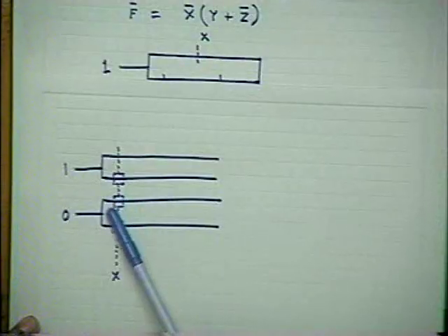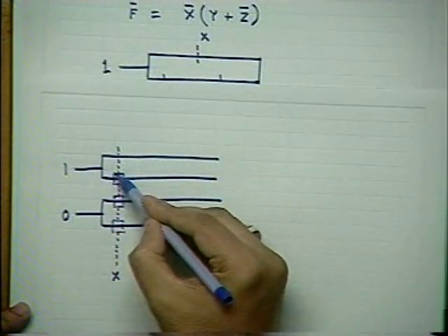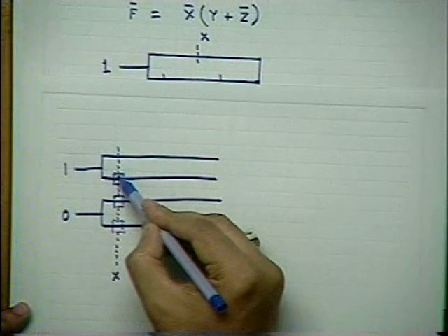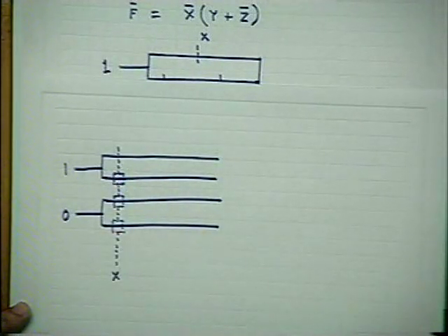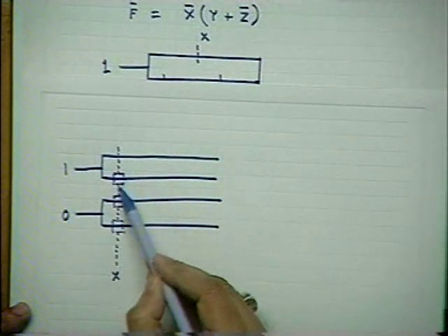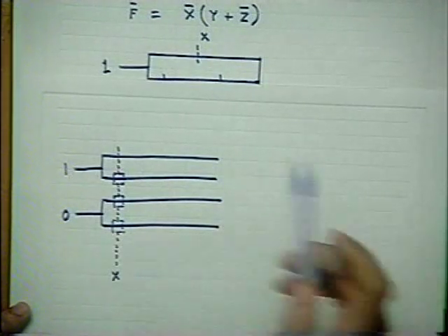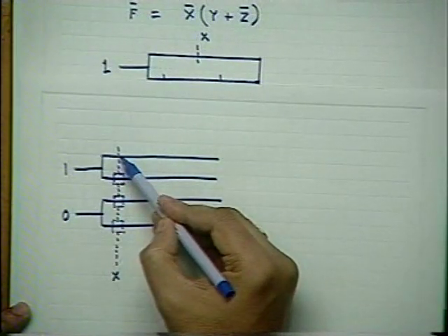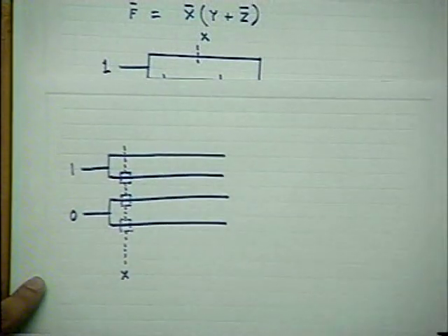So to avoid that problem, I have put these boxes. You see that I have made a discontinuity of the poly line. So the poly line has not crossed over the diffusion, and that means at these 3 points there is no transistor. The poly and diffusion are isolated. Only at this point there is a transistor. Okay.